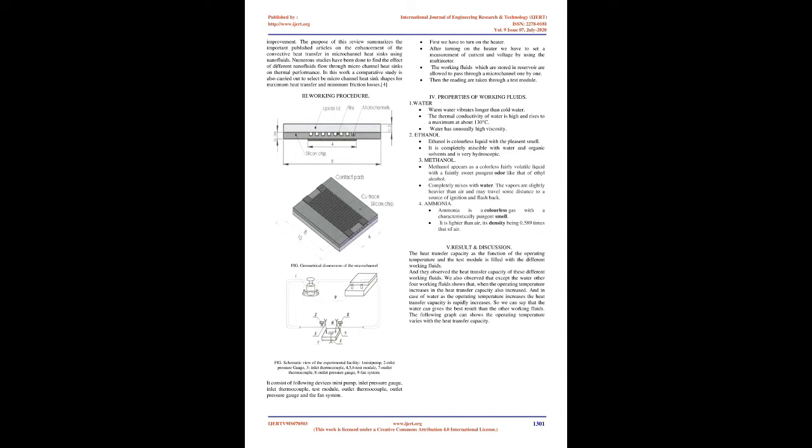Water with temperature-dependent thermal properties is used as coolant for steady laminar fully developed flow in the silicon microchannels. Using the numerically evaluated objective function, a polynomial response surface is constructed for each objective function. An evolutionary algorithm for multi-objective optimization is performed to obtain global Pareto optimal solutions. The trade-off between objectives is found and analyzed with the design variables and constraints.